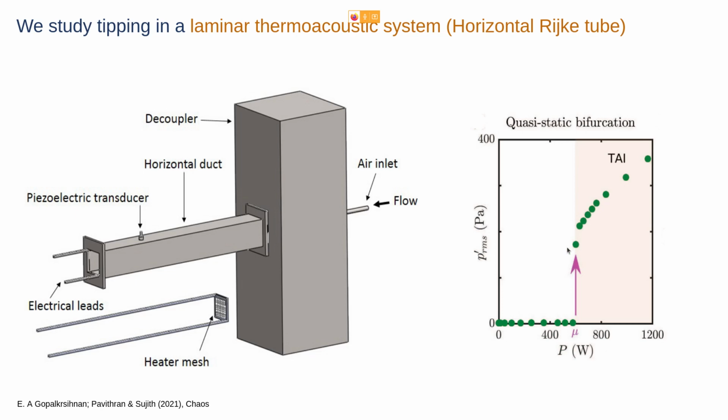These high amplitude oscillations develop due to the positive feedback between the acoustics present in the system and the heat release rate from the mesh. Here we don't have a flame. Here we have only the heater mesh, a compact heat release zone. So this manifestation of a sudden rise in the RMS is an example of Andronov-Hopf bifurcation, popularly known as Hopf bifurcation. This kind of sudden jump, and when you return back, is called a subcritical Hopf bifurcation, which we have learned. We will discuss it in the next slide.